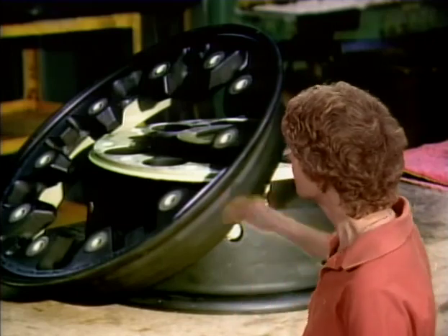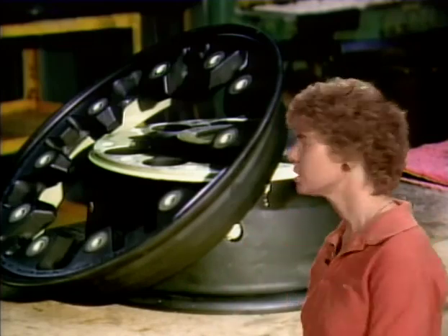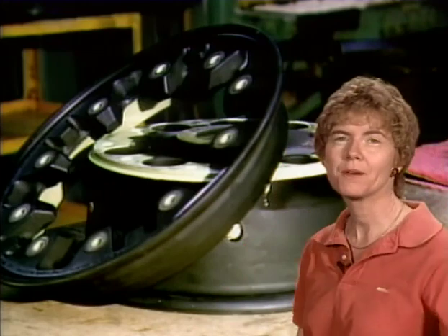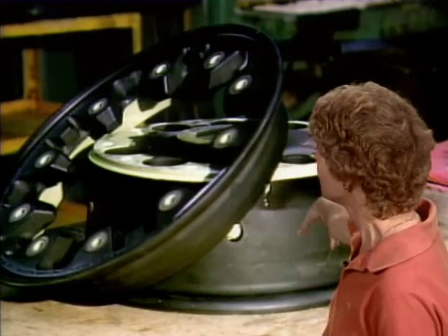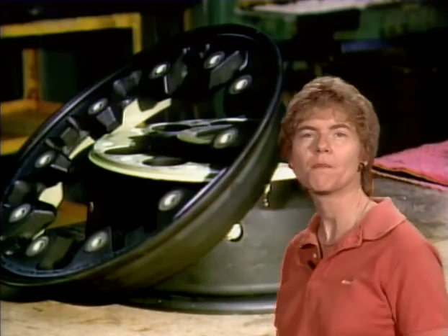And the reason for that is it's a safety precaution just in case the bolts that hold the two halves of the wheel together have been damaged or weakened. Because if they have been damaged or weakened, there is a possibility, maybe not real high, but it would still ruin your day, of the two halves of that wheel coming apart explosively, and that would be like having a bomb go off. So deflating the tire first before you even take the wheel off the axle is a good safety precaution.